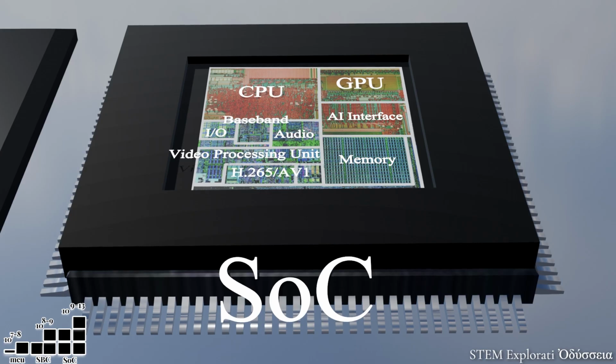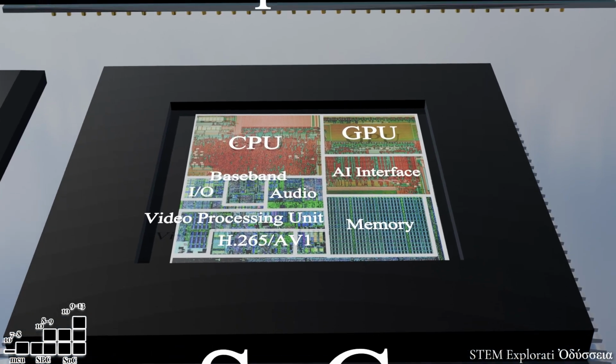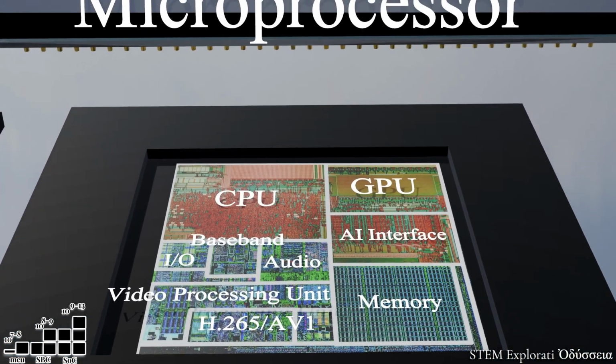A general-purpose CPU might take millions of cycles to encode a video stream, but a hardware H.265 or AV1 encoder inside an SoC can do it in real time with low power because the algorithm is literally baked into the silicon. Modern SoCs can easily pack hundreds of millions to even tens of billions of transistors onto a single chip.